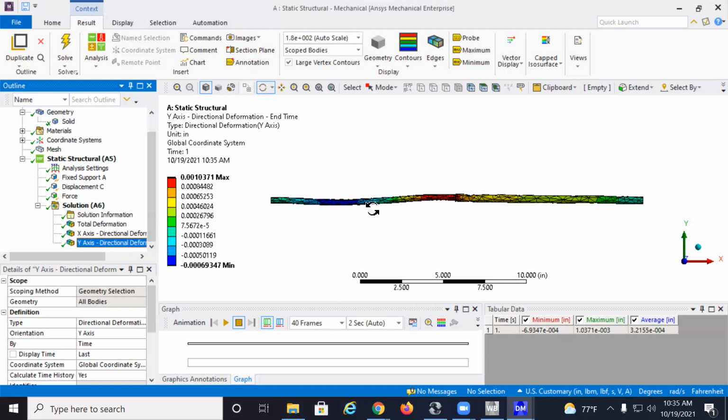Remember, this is a numerical method. When I break the part into pieces, I do not have perfect pieces to fill in the geometry, especially with the mesh size that we looked at. So this is going to contribute to the error. I no longer have a nice symmetrical part that when loaded is going to continue to move in the X direction, but it gets distorted partially because of the mesh.